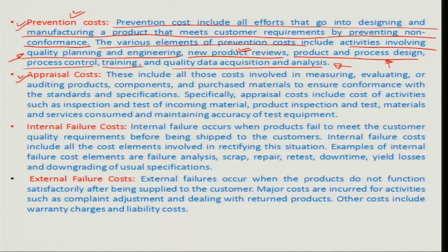For example, the diameter of a shaft may be 1 inch plus minus 0.03 inches. So this is a dimension and a tolerance given in the design itself, and the process should be able to meet these guidelines as it produces. And so how do you know that the process is meeting the guidelines? Obviously, by measuring the output diameter of the shaft which is coming out of, let's say, a CNC lathe, or some kind of a process which produces this turning.